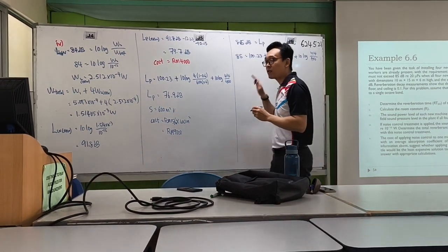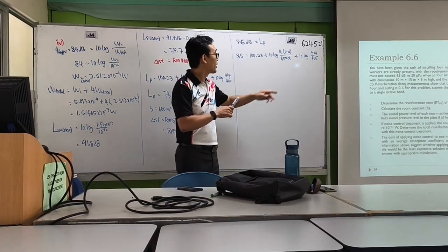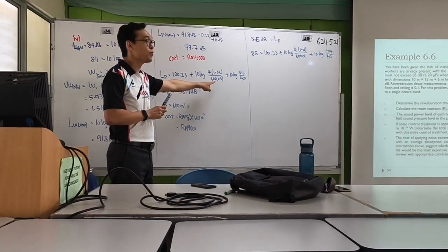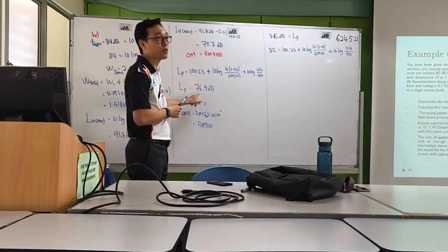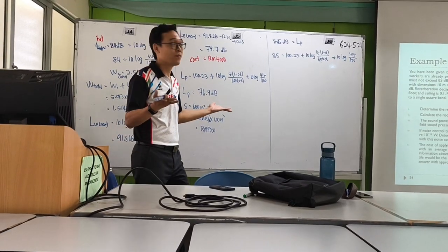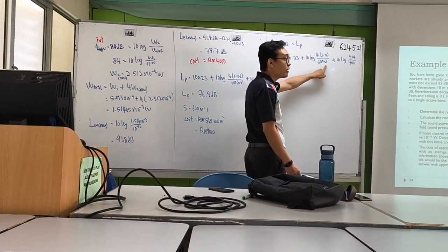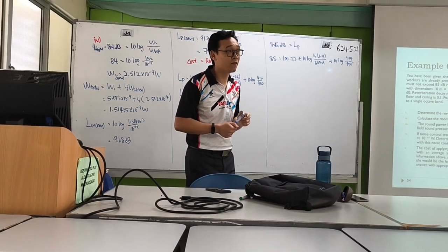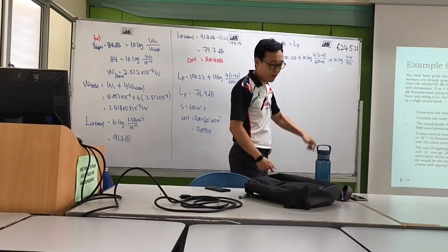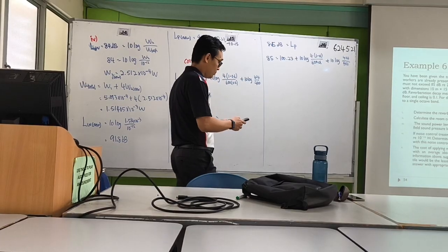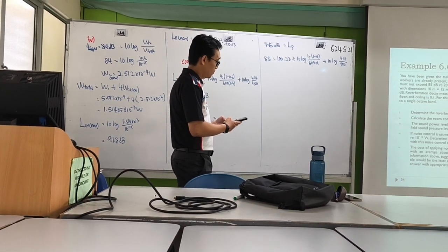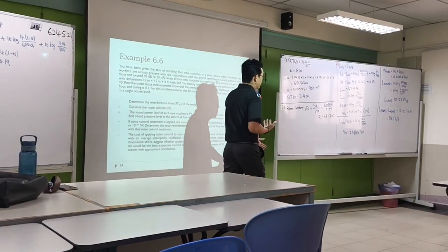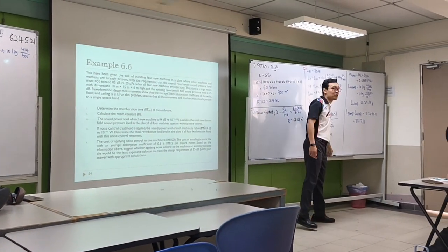So now you need to find the average alpha that is needed. Okay, it's not 0.6, 0.6 is more than that already. You see it dropped to 76 already. Actually 85 is good enough already. I want to see what is the alpha needed, then you can decide how many areas you need to cover with acoustic tile. So now we find alpha. Just need 0.19, but for my case, how many surfaces do I need to cover so that I get 0.19?